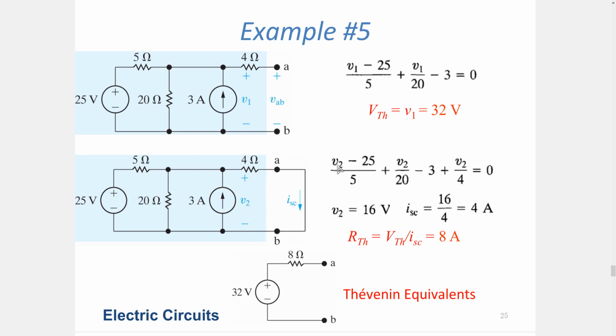So I can rewrite my circuit equations. Okay, now I labeled this as V2 in the second case because it will be different. The circuit is different, as you can see. There is the open circuit here, here is the short circuit, so its value will be different from the previous one. So I have to resolve the circuit. I'm assuming the same directions for current, and for the 4 ohm, I'm assuming that the current will be from left to right, because the short circuit current enforces it.